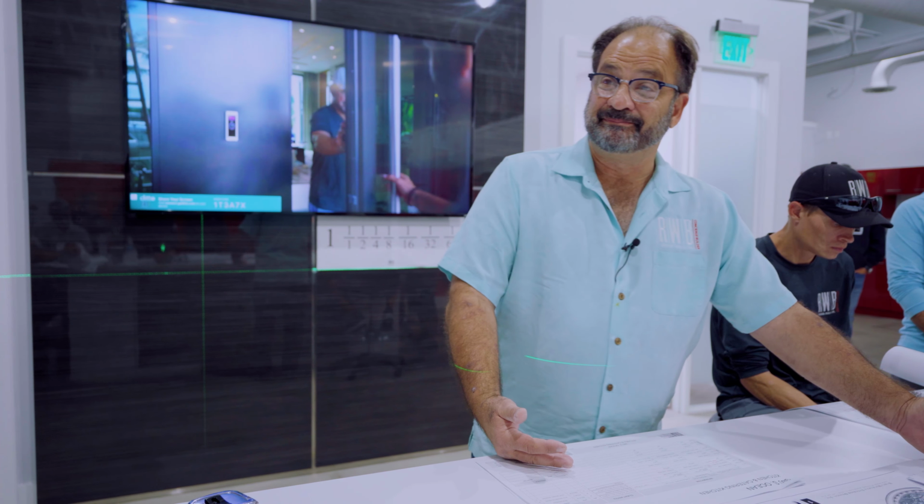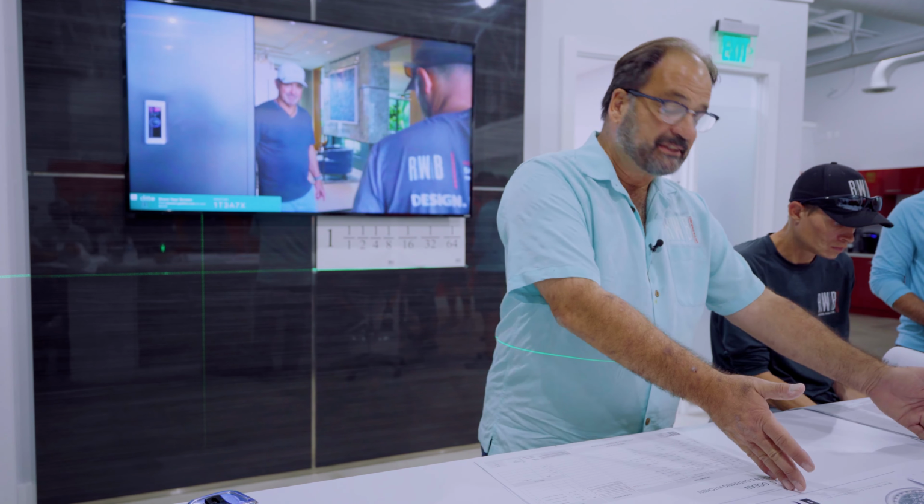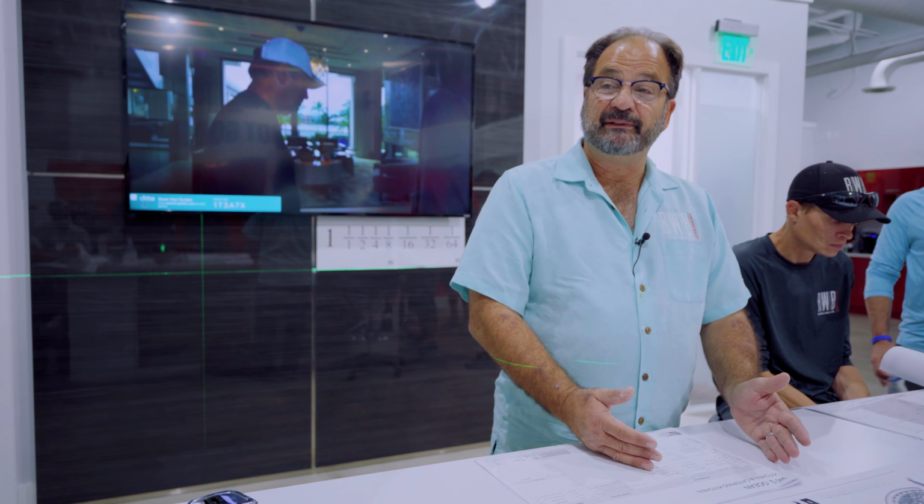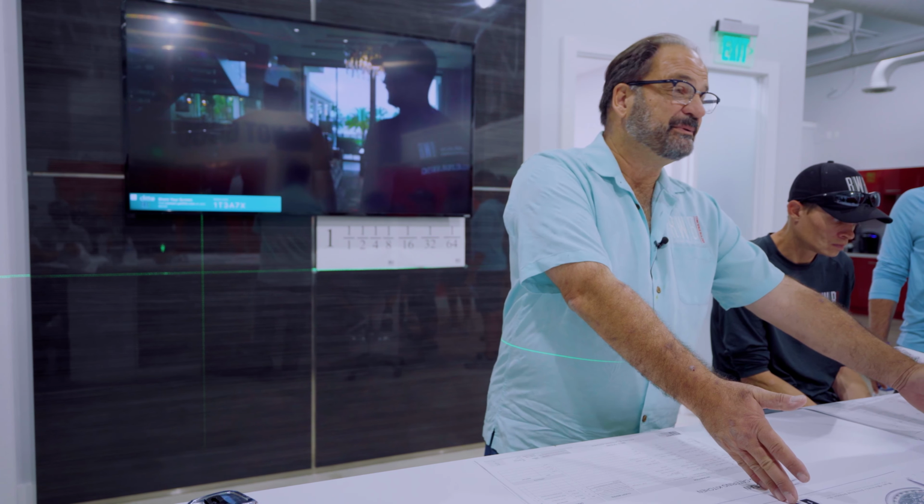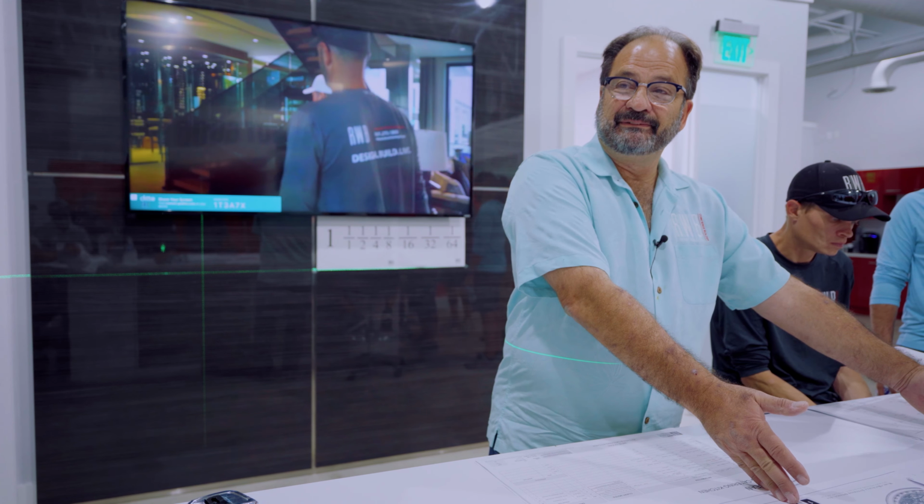stacks going through the walls, which really reduces the amount of room you have in a wall for piping. All this is important. Now, like I said, we made an adjustment on this to one of the walls. You have to think globally. If you change that one wall, what does it do to the room on the other side? What does it do to the window in the next room? If that room is centered on that window and you change this wall, are you now throwing that room out of center?